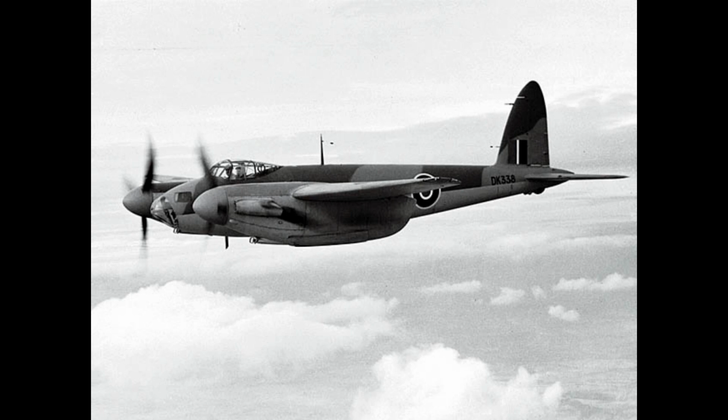Elliptical in cross section, it was formed in two separate mirror image halves using curved molds. Structural aircraft grade plywood is most commonly manufactured from African mahogany, spruce, and birch veneers that are bonded together in a hot press over hardwood cores of basswood or poplar, or from European pitch veneers throughout.